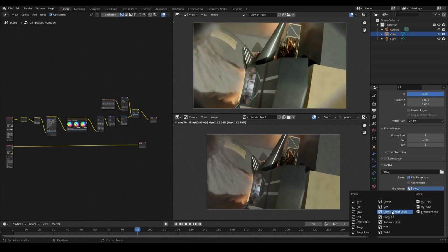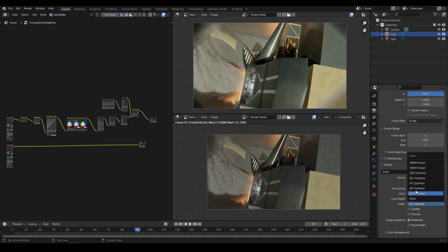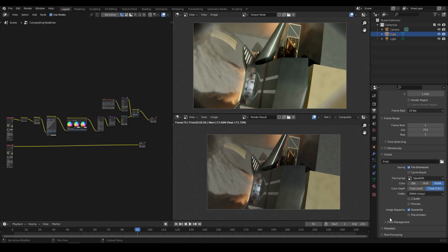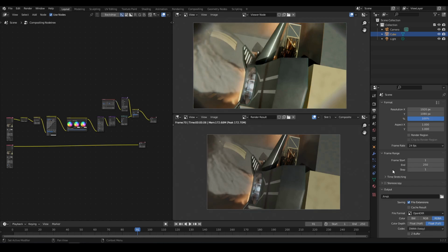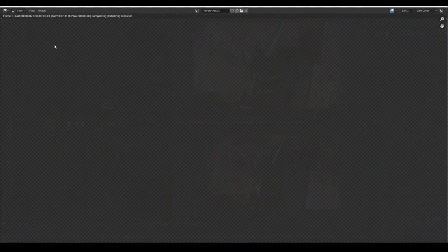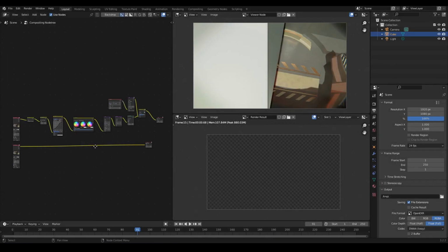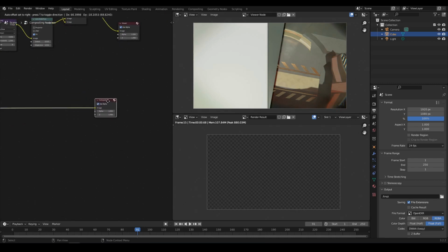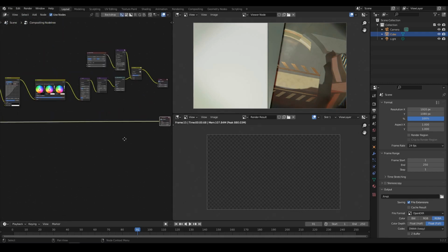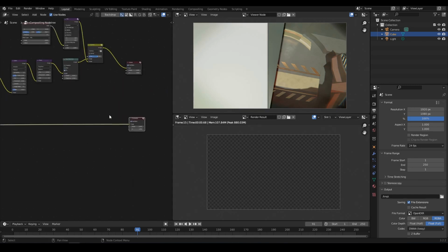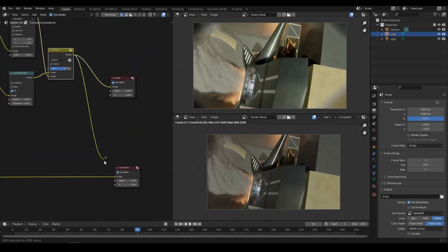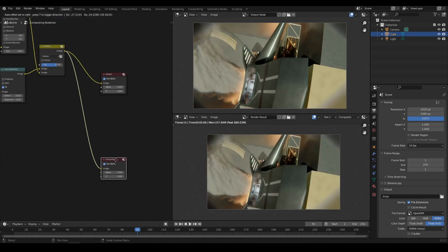And as usual, I started a render, and then of course be sure to check it sometimes, because I forgot to connect what I did to the composite node, which is where everything is gonna be rendered. If it's not connected to this, I'm not gonna render that, but just re-render the original set of images. So don't forget about that. I'm launching another render, and some other mistake you will see me doing is that I didn't set up the end frame to be the end frame of the animation. It's 120 frames, and of course it was by default 250. So remember to adjust that.